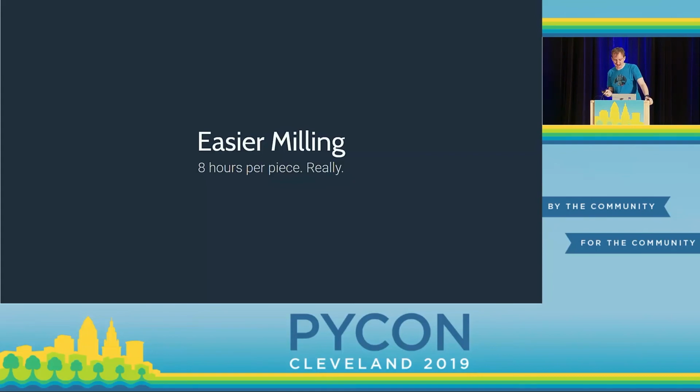There's another thing here as well: these small pieces are incredibly fragile, and the size of the milling bits you have to use to make them is incredibly small. I have broken a good 9 or 10 of them by doing it wrong and making the milling bit try and just drill into the side and it just snaps off straight away. Finding an easier way to make this toolpath stuff work would be great.